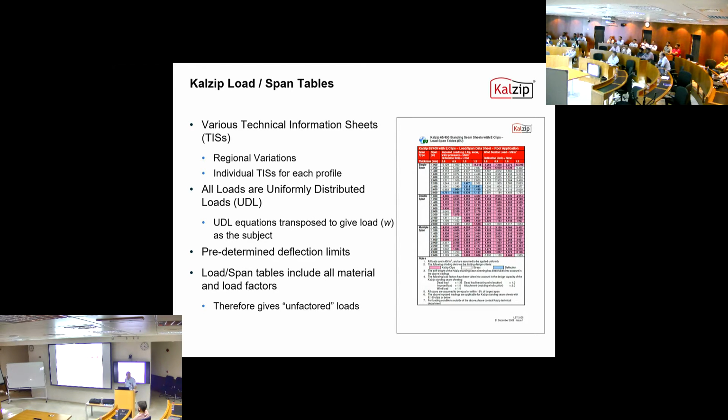Usually from experience, with the data sheets we receive from manufacturers, we are not following the maximum load, and we literally use only 60% of the load. For example, you tell me my sheet spans freely 2.3 meters, but we believe it actually spans 1.8. So does that apply for CalZip?